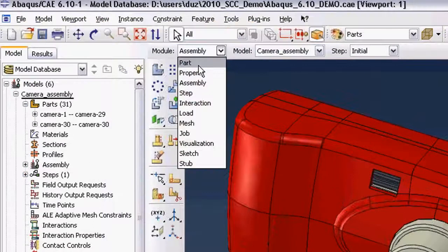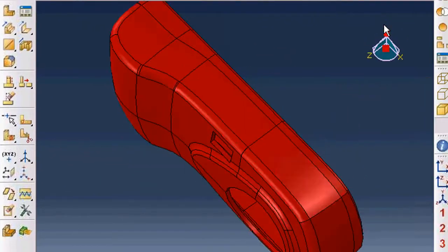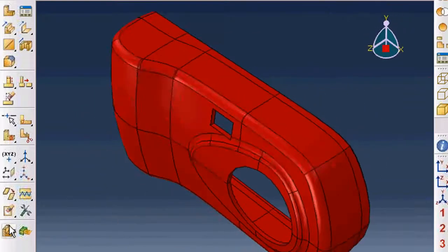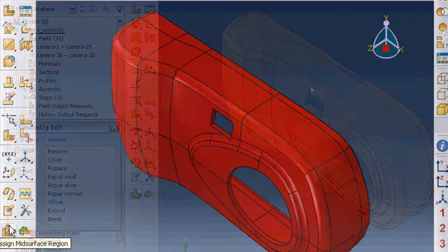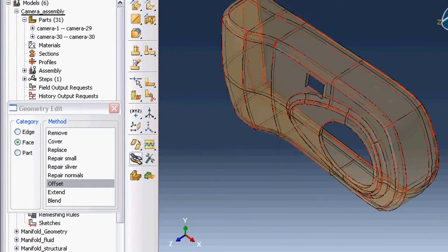that I just saw. What we're doing here is isolating the front cover of the camera from the camera assembly to first create a mixed surface part we can use for analysis. It's fairly straightforward. You identify the side from which to offset, define the distance of the offset, then identify the opposite side, then create the part.